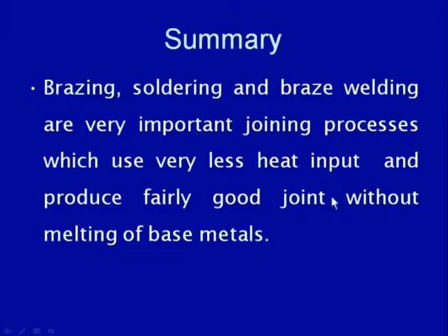So, if we try to summarize this portion which we have talked about, brazing, soldering, and braze welding, we can say that these three processes are very important, in the sense that these are solid-liquid processes where only the filler material is brought to the molten state, but the base material still remains in the solid state, and no melting of the base material takes place.